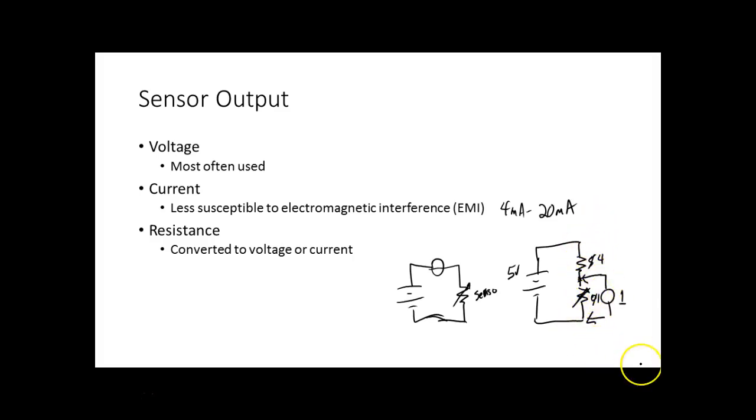And of course we could put it at the top. So we have to convert a resistance either into a voltage or into a current. This would be a system that would convert it into current, but whatever I'm sending it to would have to be here, right? You understand? Does that make sense? If I come over here and convert it into a voltage, then wherever I'm sending it to can be over here. This is one reason why voltage is probably more popular.